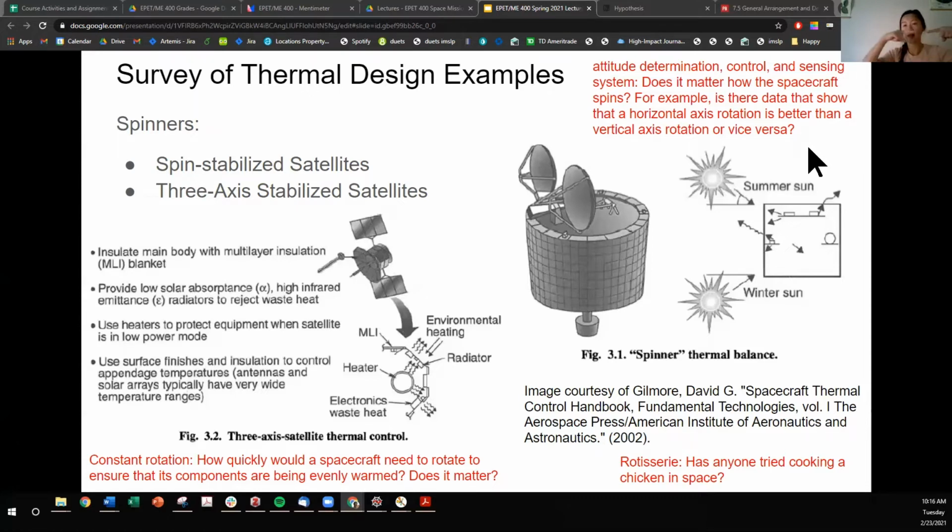Whereas if we have the spacecraft pointing like this and the solar panels are on the outside, then it really doesn't work. The sun is not facing the solar panels. It's not evenly heating the components that are mounted on the other side of the solar panels. So what you want to make sure is that the surface that you are heating is perpendicular or incident with the sun vector.